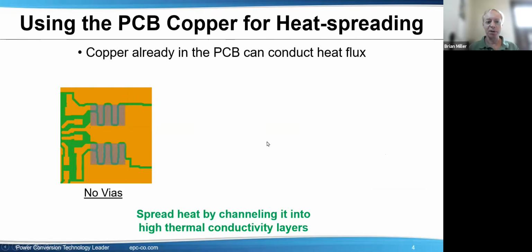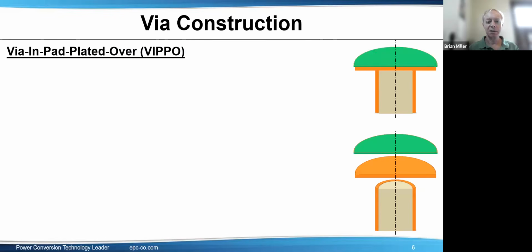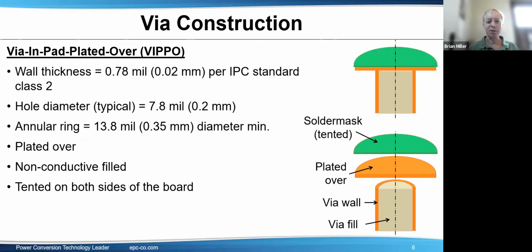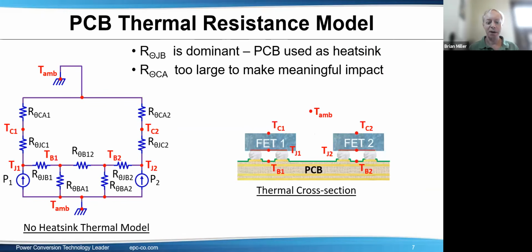If you go to a board design, in this case, a heatsink here on the top has a really great connection because there's no package on the GaN FET, so there's no plastic. This is all silicon. This is silicon wafers. You have great thermal conductivity from the junction in the red bar up to the top, and you put even a thin layer of thermal material to a heatsink.